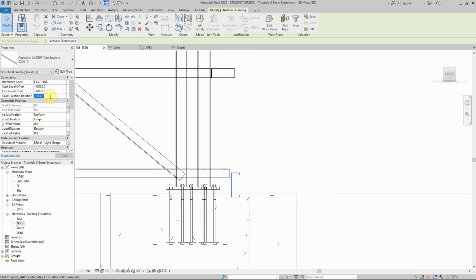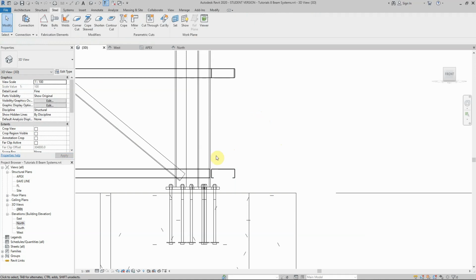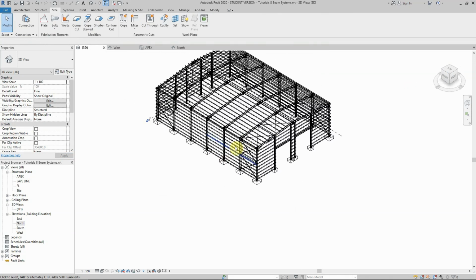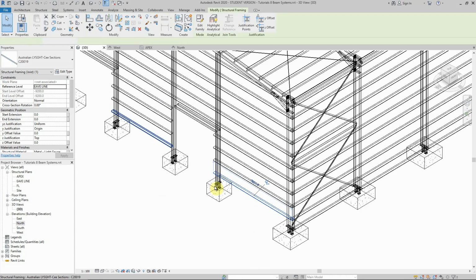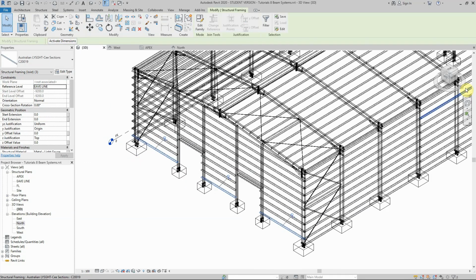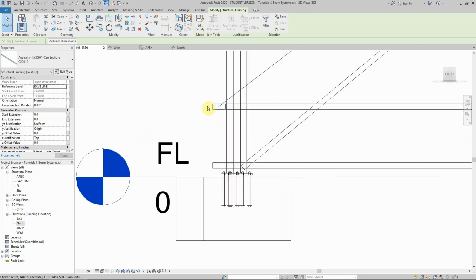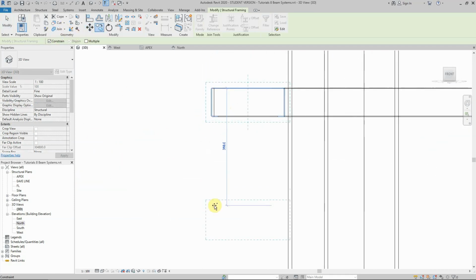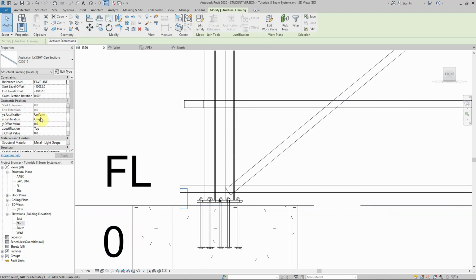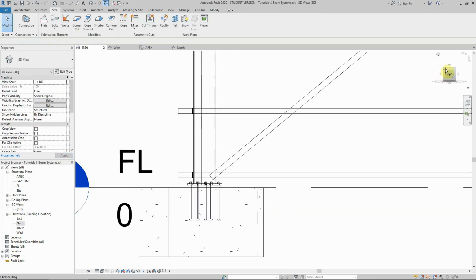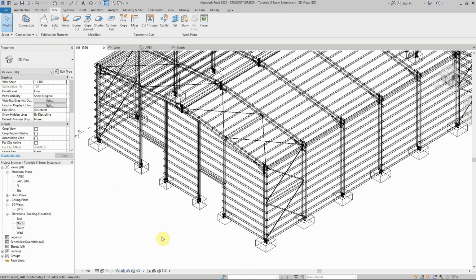For these girts only, we'll make it -90. I think from memory that worked for us. Perfect. Okay. So if we look at them, they all have the girts, and I'll double check the other face there. Copy. And we have to change -90, and that will do the job. Perfect. Okay. So we've got all these girts, they're sitting at 200mm from the ground level.